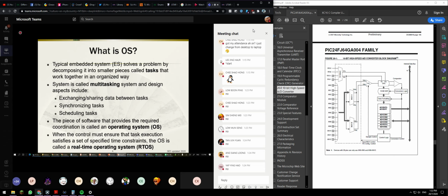The system is called foreground and background, or what do we call that? We call it a super loop, because you have while(1), correct? Whatever you are doing, your while(1) is still running. Even though you use interrupts, your super loop is still running. Don't tell me that while(1) will stop running. Like the idle task, while(1) keeps on running.